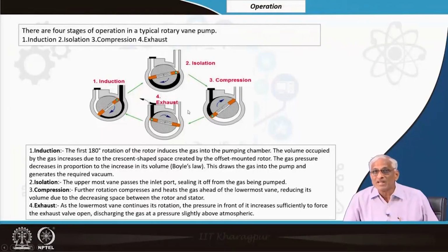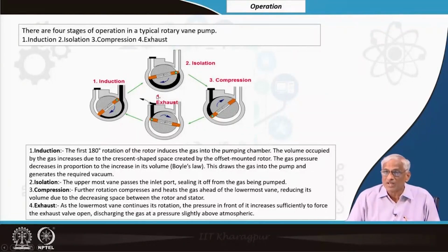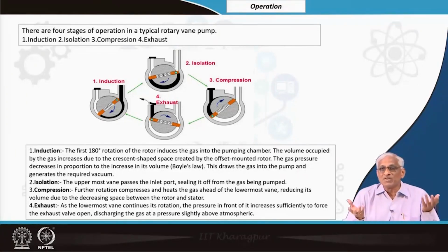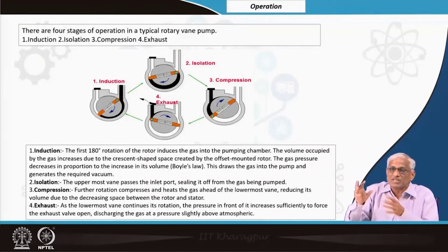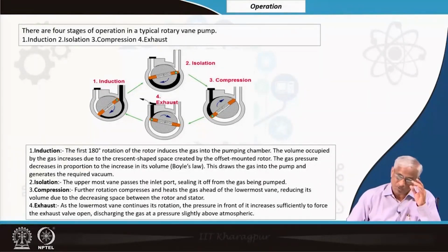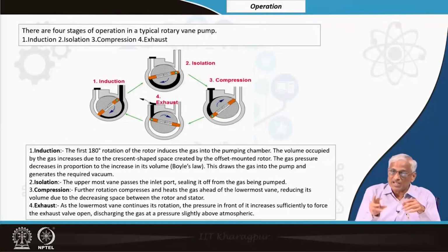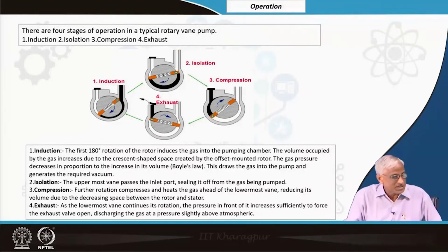There may be some leak, there may be many leaks coming from various portions, and there may be degassing from this portion. There may be compression issues, that exhaust valve is not opened, all cycles are not called duty cycle. All this together will make the net displacement 0. So, pumping speed is not there, but still you may have to run the pump because there may be small leaks which it is compensating. So, for running conditions you may have to run. Accordingly, the electrical power also may come down because loading is not much.